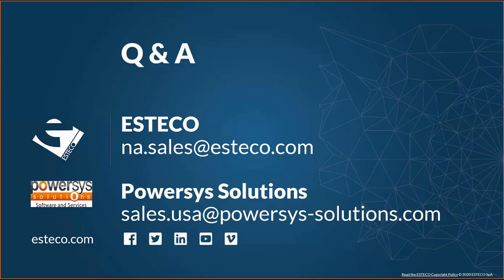Just to add on to that, all the domains can be defined based on material, and the material is a variable that can be assigned like the input constraint from the optimization, and JMAG is able to handle that part of the process coming in from modeFRONTIER. Topology optimization is possible with JMAG as well. So I think that clears it up. Basically, we can assign those materials as variables for domains in JMAG.